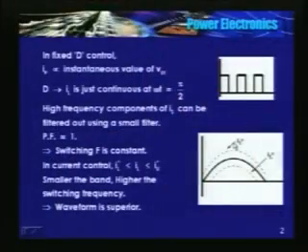So what did we do for the current control? We took a reference sinusoid, a rectified sinusoid, we called it I reference. We selected an upper band, called it IU star, then a lower band as IL star. We control the inductor current within this band.